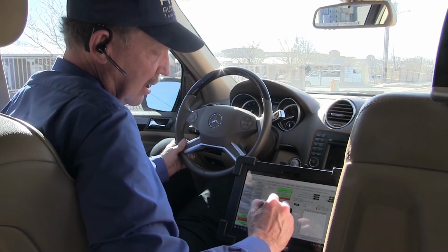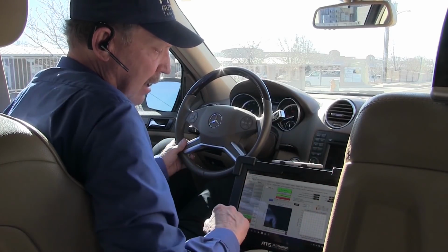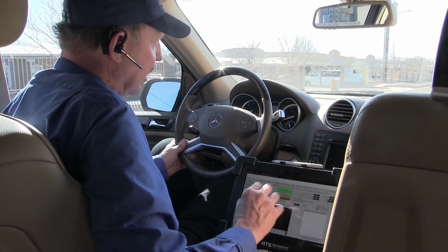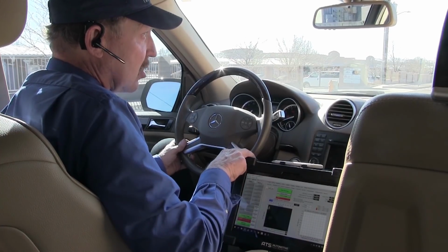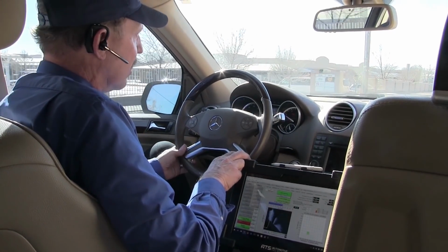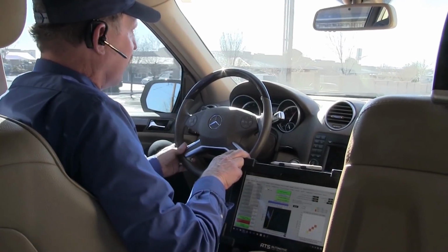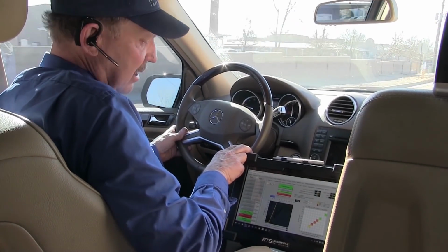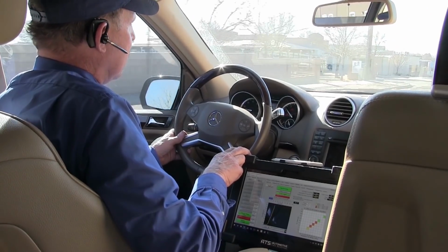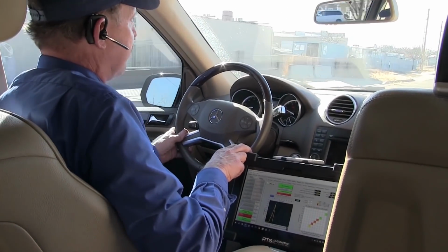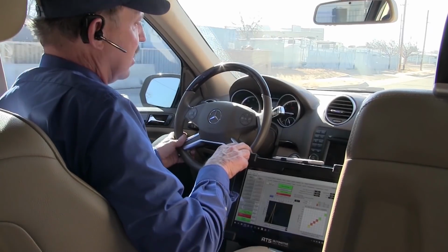Now what this test is going to do is compare the actual mass air sensor to an engine model that's programmed into this. What I want to do is make sure it's not something being read wrong with the mass sensor, and that's what this is going to do. So we roll along and we floor it in first, and we let that graph up, and we can see that it didn't quite follow it correctly. So let's just stop here and look at this real quick so I can see what's going on.